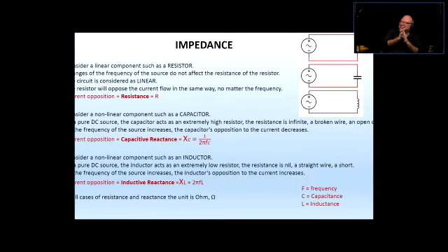Okay, we're talking about the reactive resistance of capacitor. So you lower the frequency, capacitor is going to give you more resistance. You raise the frequency, the capacitor is going to give you less resistance. Capacitors love change. Right? Higher the frequency, the less resistance the capacitor is going to give you.